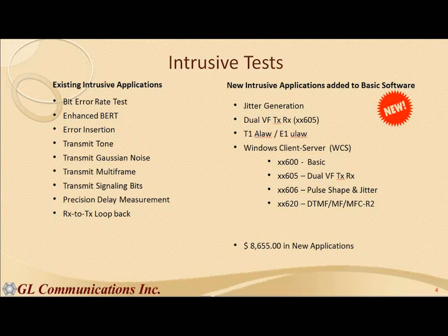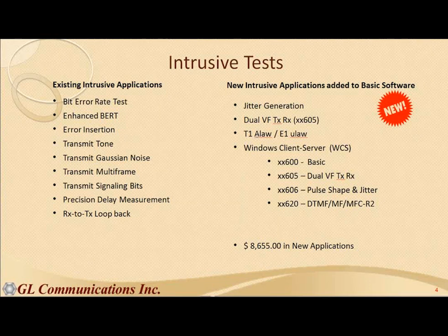Japan and the United States are the only countries that use mu-law. As soon as you leave those countries, you enter the A-law world, which is E1. And when you digitally transmit between such countries, you have to abide by the receiving country, and you have to convert from A-law to mu-law or vice versa. So it's possible that you could have misconfigured the system. So that's there as a feature.